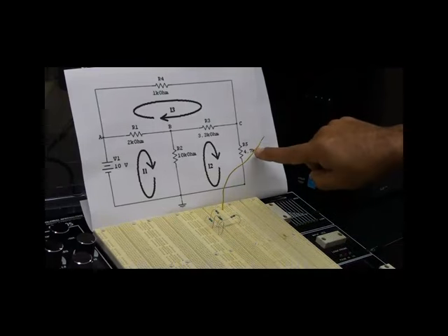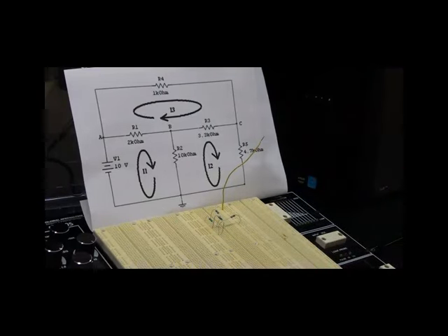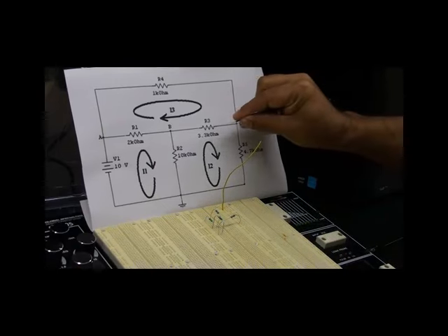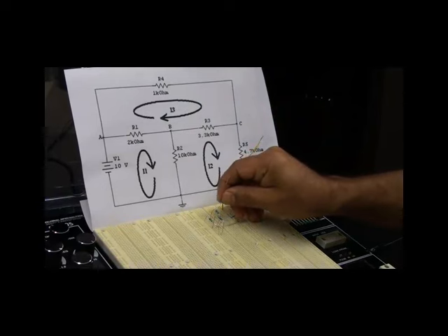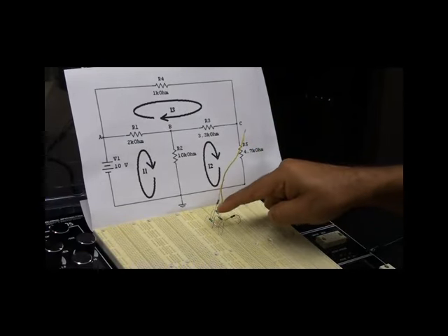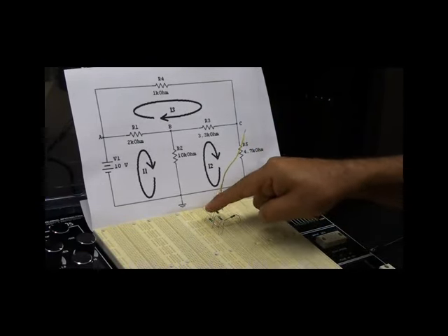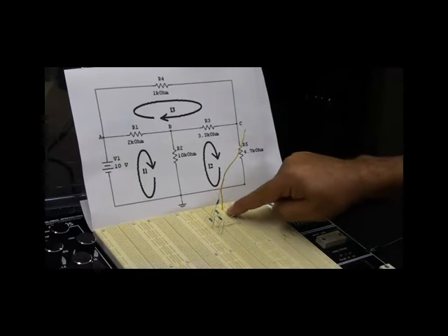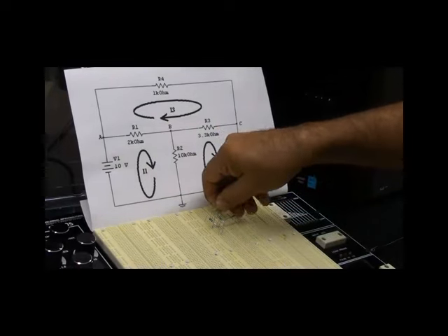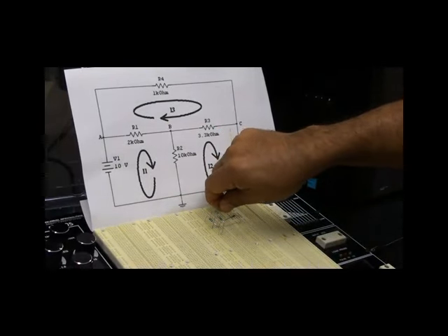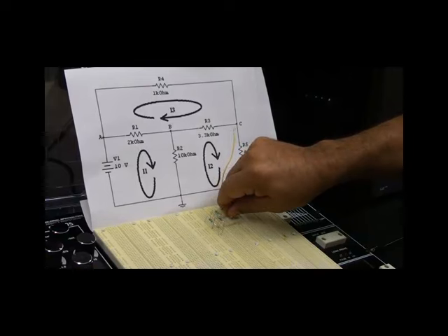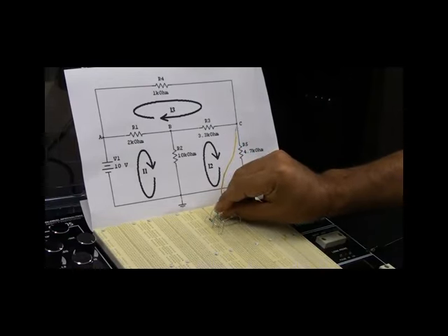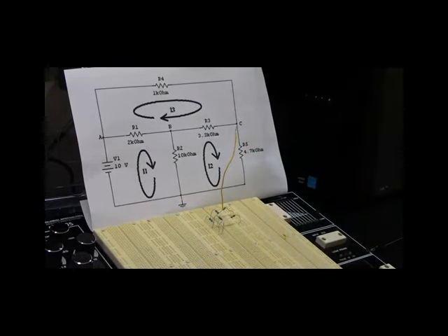Now it's the time for R5. R5 from one side is connected to the shared point of R3 and R4, which is here. Because this was R3, this was R4, the shared point is here. And then it goes to ground. We already considered this to be the ground. So I'm going to connect it to another hole on the ground. So you see that the topology is preserved.